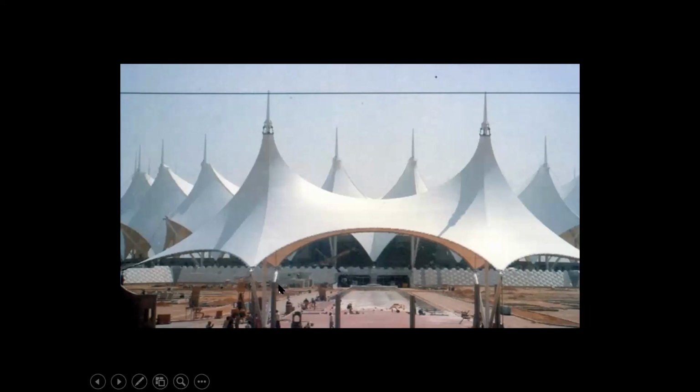Here's a mast. That's the central mast going up to create a high point. And here's the low point here, created by a compression member and a tension tie. And the edges of these structures have cables, like this is a catenary cable here. And the main structural element is the fabric. In this case, it's woven fiberglass coated with Teflon, the same stuff that we use on our frying pans to stop dirt from sticking.